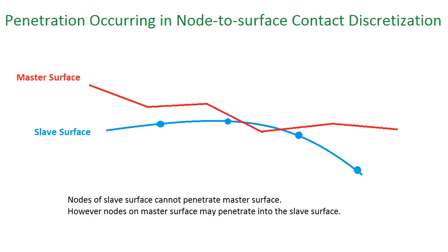The surface-to-surface contact formulation, on the other hand, considers the shape of both the master and slave surfaces in the region of contact, and enforces the contact conditions in an average sense over regions near the slave nodes rather than on individual slave nodes alone. Large penetrations of master nodes into the slave surface do not occur with this discretization. Hence, the choice of master and slave is not as important, but the same surface selection guidelines as node-to-surface discretization should be followed where possible.